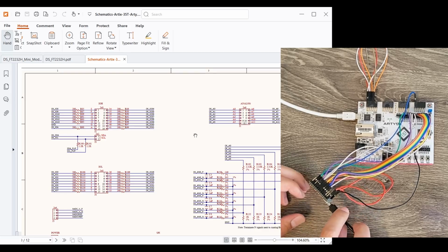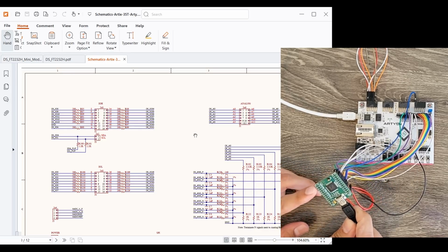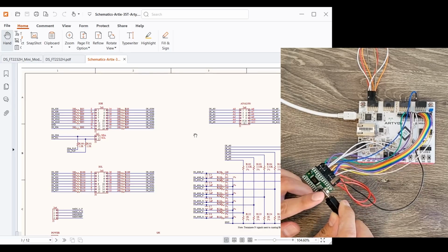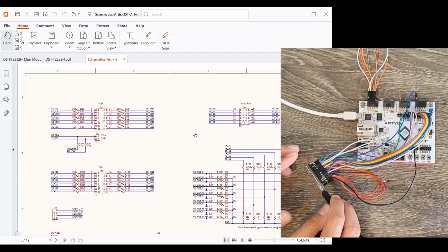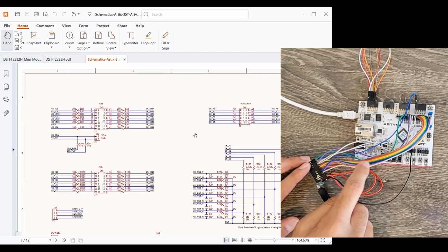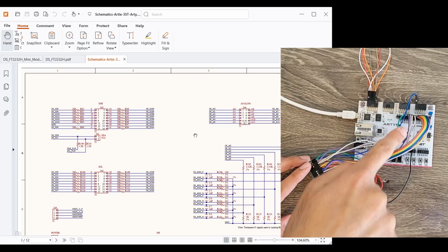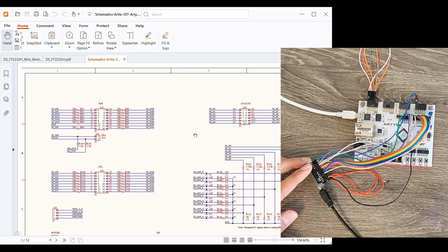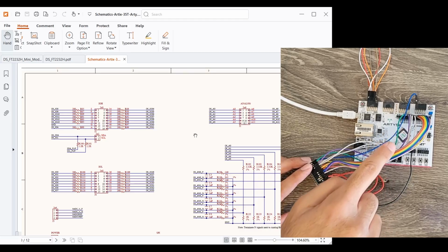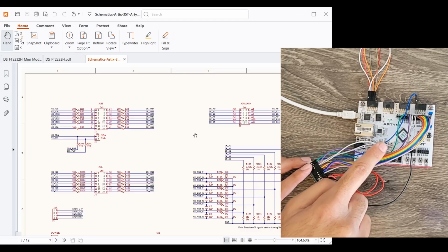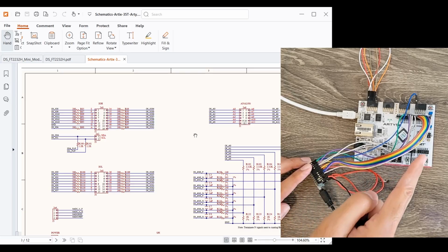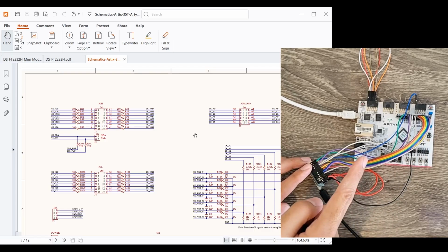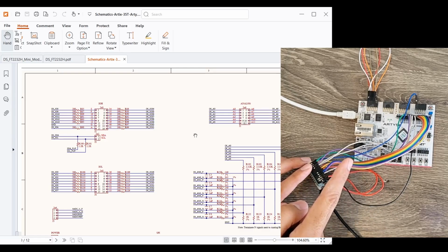So if I want to show here, this is the mini module, and these are the pinouts, and based on the mapping that I had from these datasheets, I connected all the required pins to the Artix. We are going to see in the next video how the constraint file in the Artix is defined, but basically whatever we connect from this FT2232, we just need to keep track of the mapping, and then in the constraint file in the FPGA, just assign those pins.